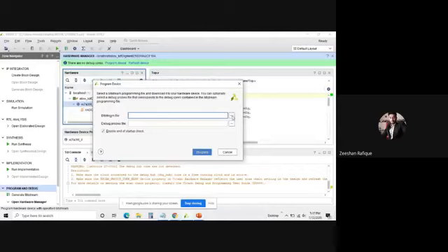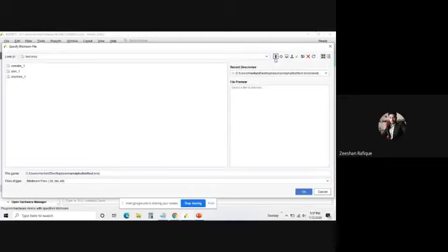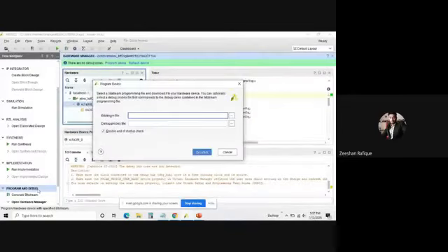So it will ask for your bitstream. Okay, and now you can search the bitstream file here. I think I have the bitstream file. Okay, so I haven't created it because of the shortage of time, but I think it will be there. Constraint file new. Okay, no, we don't have. So once you click on generate bitstream, it will generate the bitstream file, and just port it here and click on the program button. It will upload your bitstream file into the FPGA board.